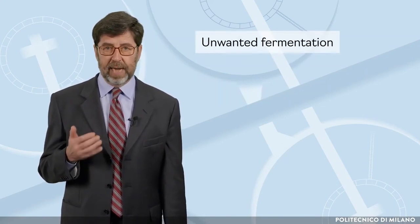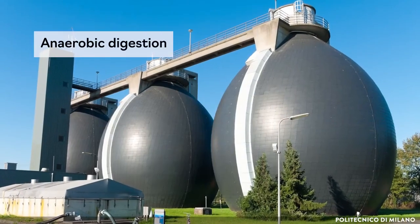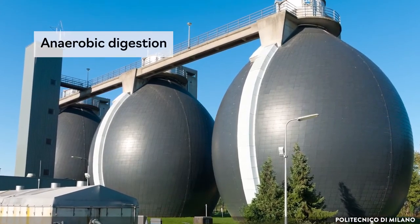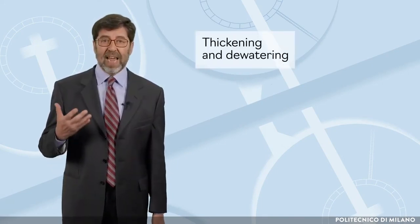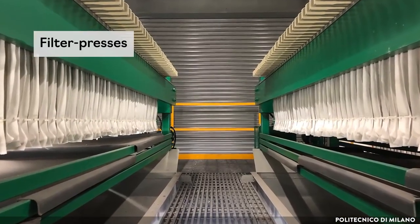This step is essential to reduce the risk of unwanted fermentation and putrefaction processes, which produce bad-smelling compounds and favor the development of microbiological contamination. Anaerobic digestion is an effective process that also produces biogas from which we can recover energy. Second, reducing the water content, which means reducing its volumetric flow rate. Thickening and dewatering are the treatments that aim at reducing the water content. Belt presses, centrifuges, and filter presses are the most widely used technologies.